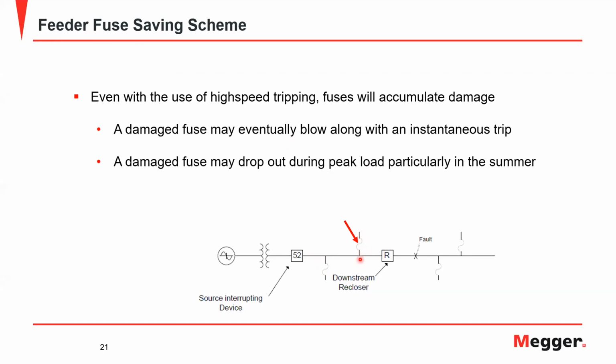Most fuses actually have a spring inside that holds tension on the link. The spring is used to accelerate the movement when the link parts, so that it helps to interrupt the fault. That tension, a little bit of accumulated melt if it gets hit with 3–4 faults over time, a little bit of micro vibrations with the wind going on, and you can have a fuse just give up and drop out at an unpredicted time. It might be associated with another fault on its branch, but it might not be. It's very hard to say. It could be the summer sun is the final factor.